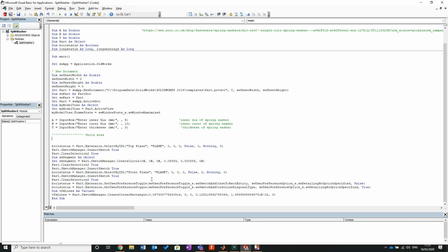So one issue that I'm going to want to be able to do is actually put a fillet on these edges. Because if you look at any spring washer, the sharp edges don't tend to be there. They've been ground down, they've been treated. So I do want to put a fillet on there. Even though I don't know what that will be, I'm going to add a control on afterwards to give me that control. Anyway, so I'm going to A is equal to A divided by 1,000.